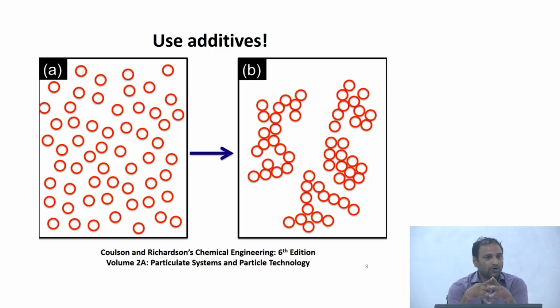People put in what is called alum, which is aluminum sulfate, a salt that is typically added to water to ensure that whatever dirt particles are there in water become larger in size. And the moment such water is stored in a tank, they slowly settle down, and therefore you can achieve water purification. So one way of doing this would be additives, right?